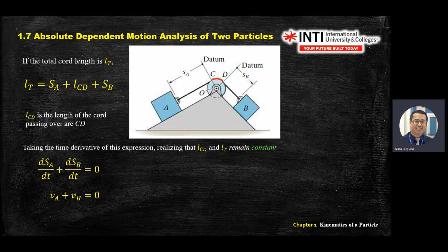This is the equation that we're looking for when a pulley system comes up in the question. Right, this is what we want. Then you rearrange. You can put either VB or VA on one side. If you pull this one, you will notice that velocity of A and velocity of B are always opposite of each other. Like the simple logic, if you pull this one it will move up. Important is this one. Then you rearrange this one to solve simultaneous equations later.